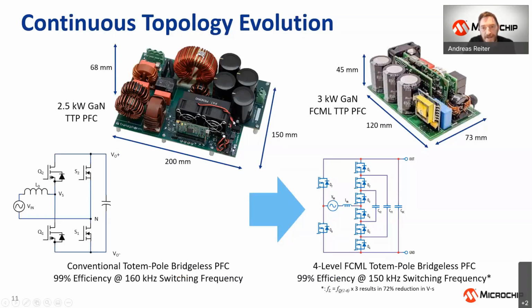Down here, you have maybe half a square centimeter of space where all the probes need to go, and that's right in the middle of high voltage. So that's not very convenient. And given that probes sometimes just slip and might scrape over the PCB, it's also really a safety hazard. Things are getting more tense as these designs start to evolve.